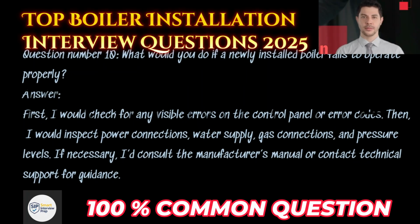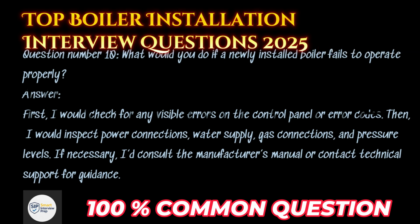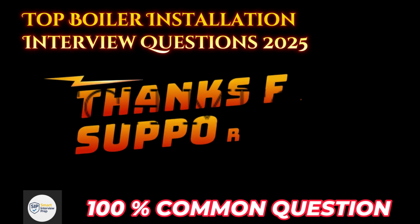Question number 10. What would you do if a newly installed boiler fails to operate properly? Answer. First, I would check for any visible errors on the control panel or error codes. Then, I would inspect power connections, water supply, gas connections, and pressure levels. If necessary, I'd consult the manufacturer's manual or contact technical support for guidance.